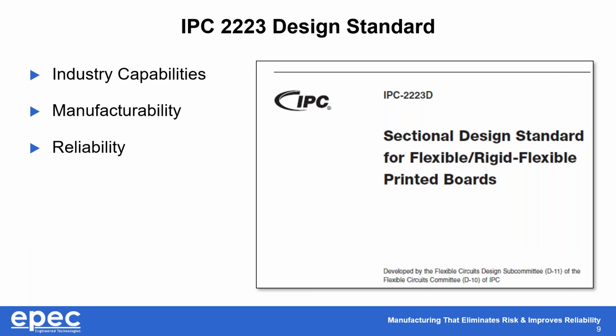A key element in the DFM process is applying the guidelines that IPC has established in their 2223C sectional design standard for flex and rigid flex printed circuit boards. This standard covers quite a lot of ground. It's very detailed, deals with a lot of the capabilities that are present in the industry, deals with a lot of items that relate directly to the manufacturability and also to the reliability of the finished part. This is our Bible.